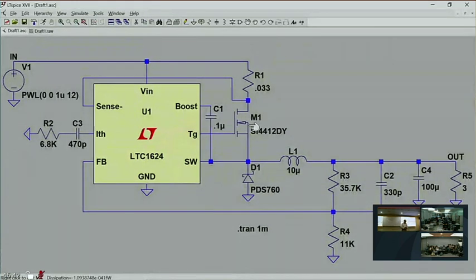When you turn this switch on, you want it fully turned on, because the power associated with any voltage drop across the switch will be dissipated as heat in the switch, whereas the power associated with the voltage drop across the inductor will be stored as energy in the flux of the inductor. So the whole idea of a switchboard power supply is you withstand voltage with an inductor instead of a switch.